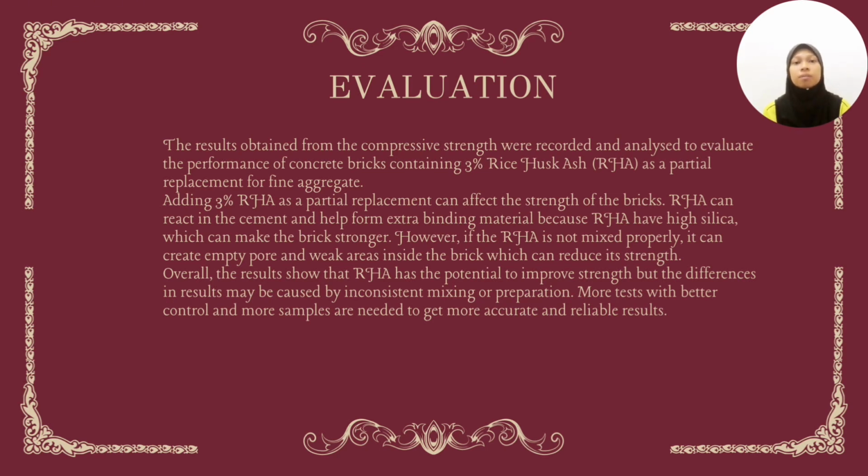Evaluation. The results obtained from the compressive strength test were recorded and analysed to evaluate the performance of concrete brick containing 3% of RHA as a partial replacement for fine aggregate. Adding 3% RHA as a partial replacement can affect the strength of the brick. RHA can react with the cement and form extra binding material because RHA has high silica, which can make this brick stronger.